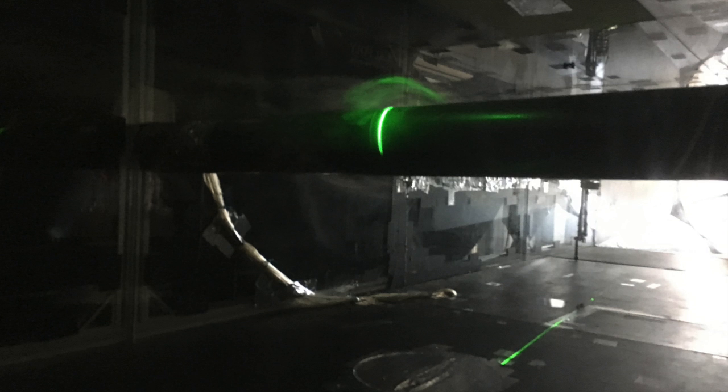After running the wind tunnel for both velocities, with both a smooth cylinder and with sandpaper strips attached to the cylinder, we began to put smoke through the wind tunnel while illuminating the smoke with a laser to aid visualization of the airflow around the cylinder. The laser was positioned in two different orientations, perpendicular and parallel to the cylinder.